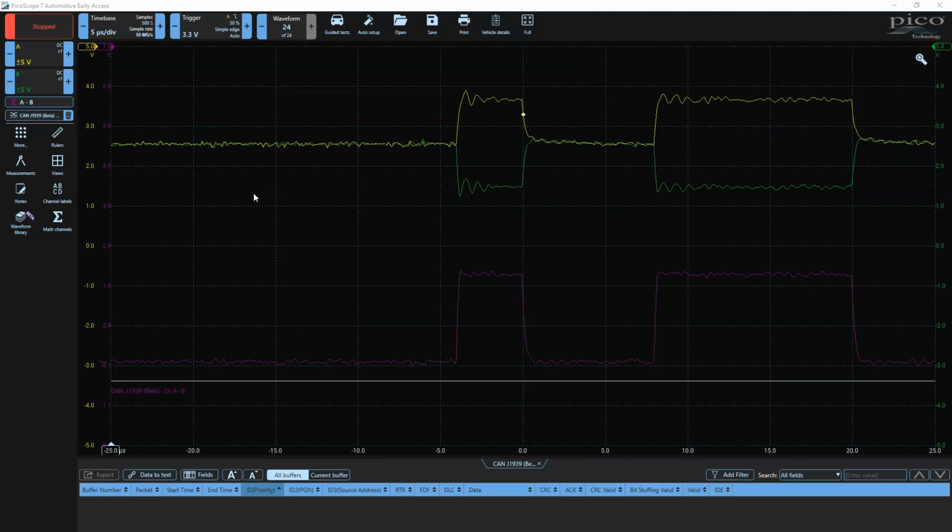I'm probably not going to cover anything with active termination for a couple of reasons. For one, I don't know, other than perhaps with ag, maybe for the ISO bus or the implement bus, if active termination is still in use. I think it has been phased out. Basically, active termination, instead of having 120 ohm terminators, we have active electronic components which try to hold the CAN bus, CAN high and CAN low, at 2.5 volts, and would have resistors in series.